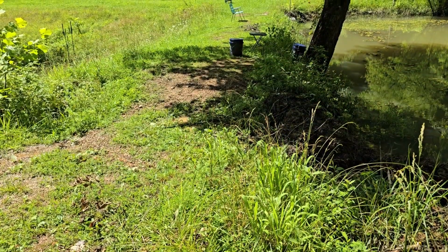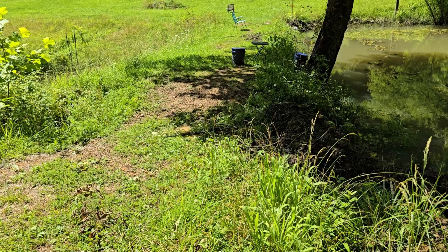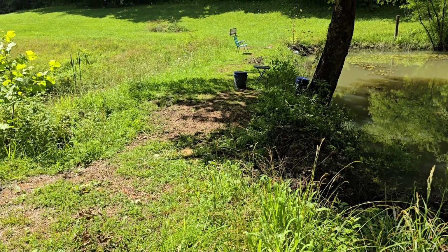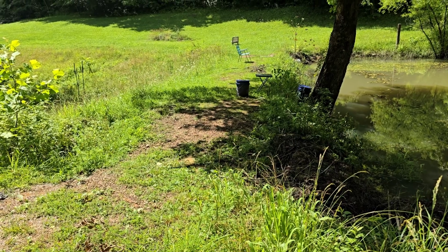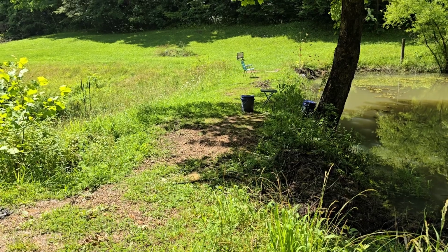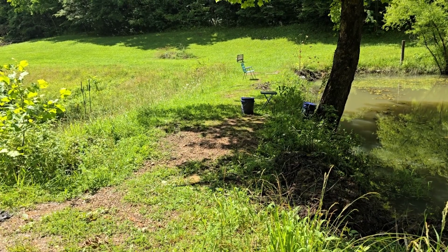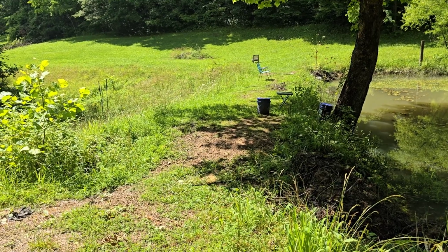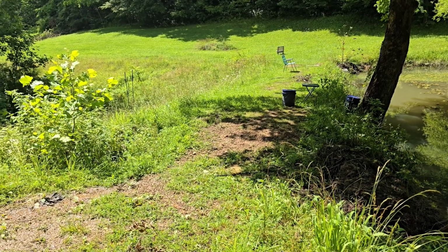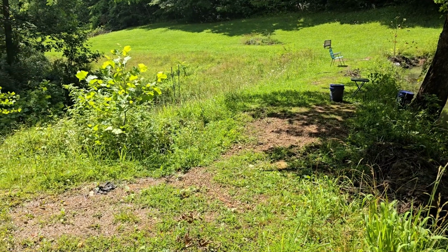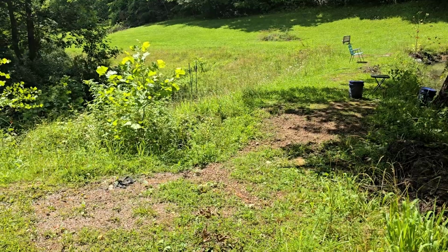DJ Bushman, a private landowner in eastern Kentucky, contacted me because he was concerned that beavers were damaging a dam that had been constructed by a previous landowner on his property. The dam had been built across a narrow valley with steep slopes to create a 1/2-acre pond. The dam had a narrow top with steep side slopes. No spillway had been built to carry water around the dam. Drift on the dam showed that water had flowed over the dam during a recent storm.